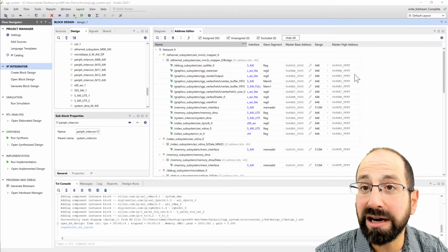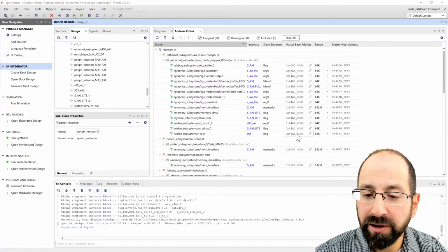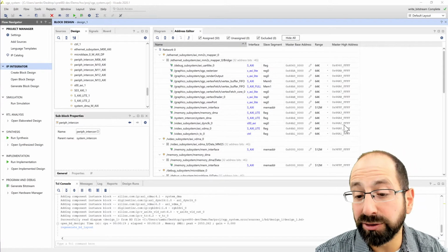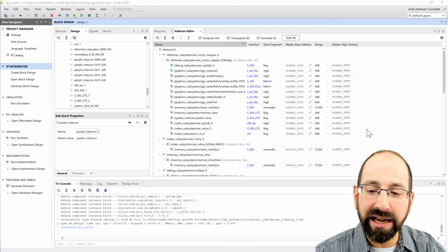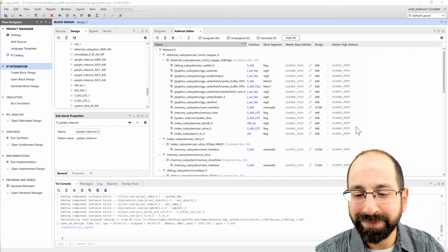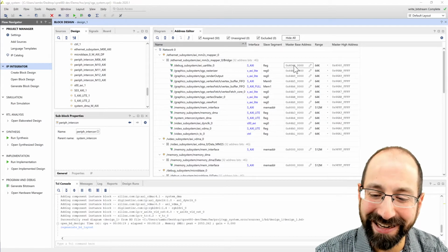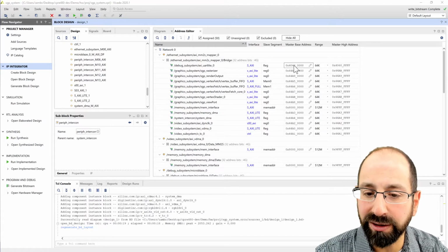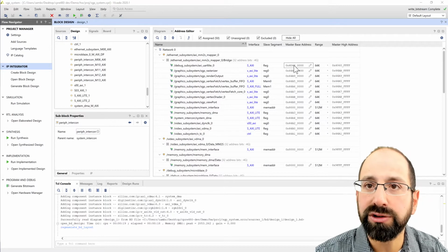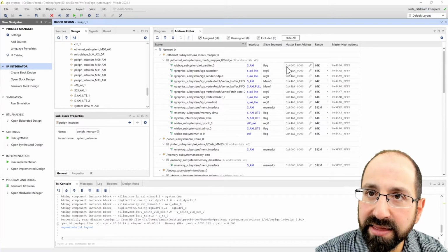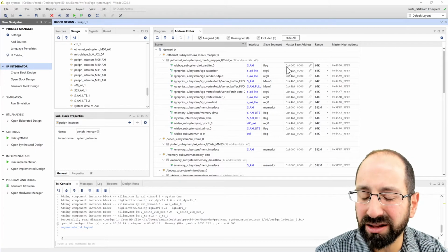So right now, since we're not changing it all that frequently, we keep these fixed and we update our driver as need be, right? A driver change takes a minute to test. Changing any one of these values takes 30 minutes to an hour to test because this does require a synthesis rebuild, a bit file rebuild when you change any of these values. But then this is where you can see that kind of glue logic in the driver.